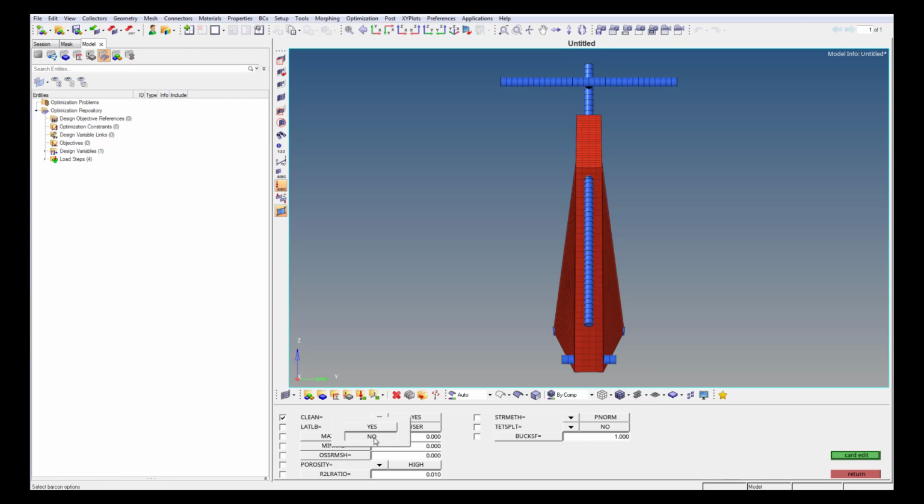Porosity defined as low will lead to a final design with mostly fully dense material distribution, and is appropriate if compliance minimization for a given target volume is required. The amount of intermediate densities in a model depends primarily on the penalty applied. This is similar to the penalty applied during a topology optimization. In the optimization view, we can see the newly created cards and review them in the entity browser.